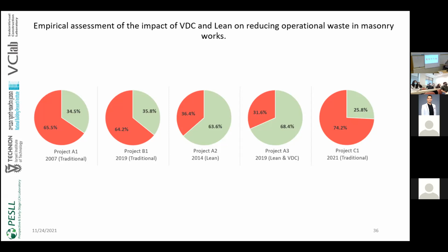It's a traditional project, but the difference between this project and the other 4 projects is that the last projects used gypsum block and Eton block, which have the same construction method. You build all the blocks without need for columns and beams. Now, the new project, project C1, which I studied, is concrete block. So the construction method for the concrete block requires each 4 meters to make a concrete column, and after each 10 rows, you need to make a concrete beam.